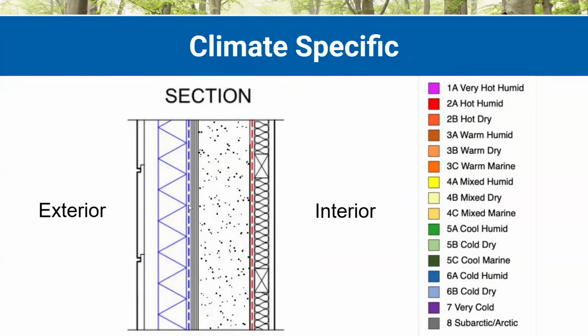So most of our membranes tend to be quite vapor permeable, and we're sometimes relying on the sheathing for that lower vapor permeability. So OSB has a lower vapor permeability than plywood, but in general, I like how plywood responds to moisture if it is getting humid around it than OSB.